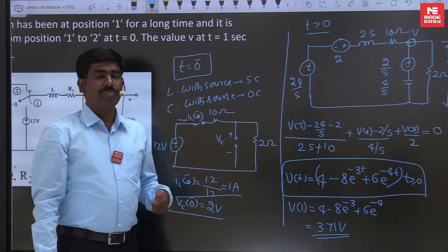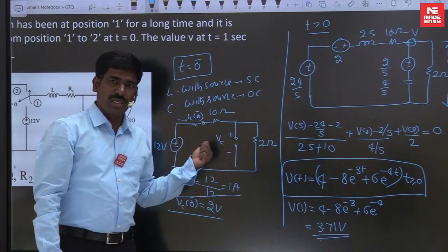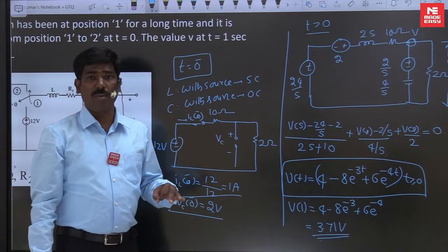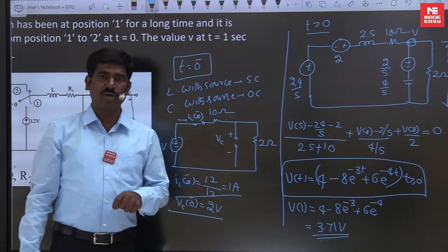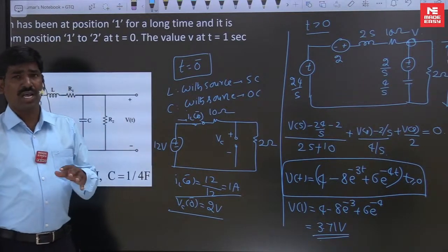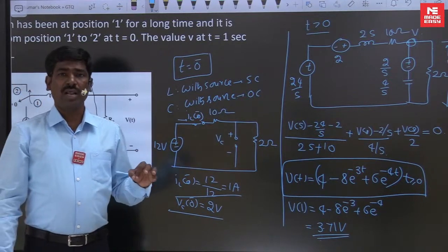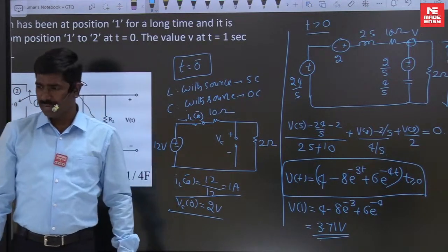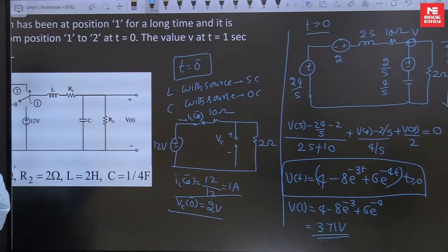इस वजह से you are using a Laplace transform technique. इस case में don't use the formula final value plus initial value minus final value e power minus t by tau, use ना करना है. That is only for RL and RC circuits के लिए. Okay. Right, very good. 3.78 is correct.